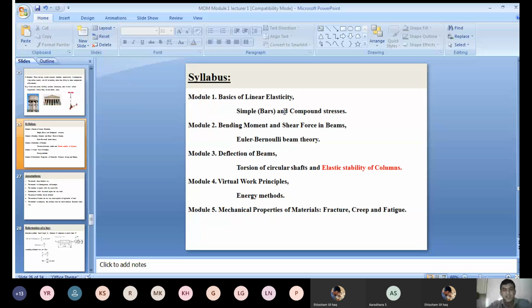Deformation that takes place perpendicular to the loading direction, or perpendicular to the axis, is called lateral deformation. The change in shape of a body due to a shear load applied on the body is called shear strain. Then we discussed the stress strain diagram.